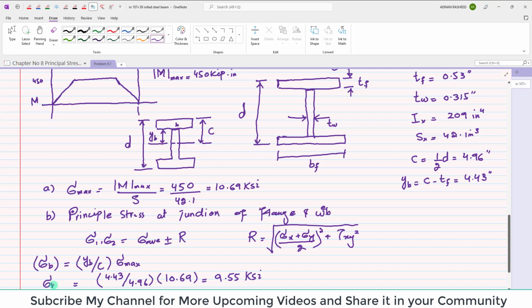So again the stress is reduced, normal stress is reduced at this point. Clear? So normal stress is maximum at the outermost surface. If you come down toward the neutral axis, the normal stress will decrease, and you can see it is 9.55 at this point B. So sigma B here will be equal to 9.55 KSI.